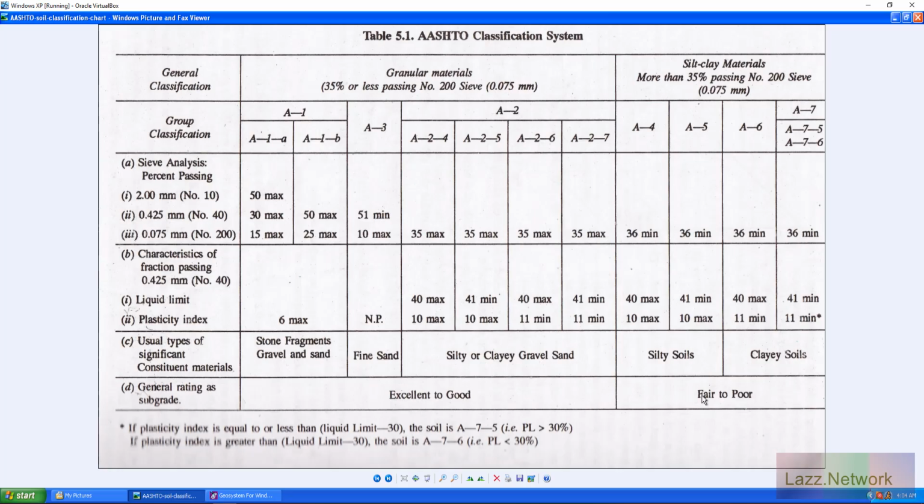It doesn't mean that if it's a poor material that they won't use it. It just depends what the intended use is going to be. More than anything, if it's closer to the base of the road, or the stabilized subgrade, or closer to the subgrade levels, unlike for fill or embankment, you probably don't want to use this material. That's all that's indicating, honestly.